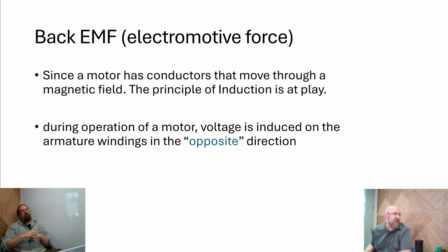This is the thing that I think a lot of people struggle to wrap their head around the first time we talk about it, because you really have to have a solid understanding of how induction works fundamentally before we can dive into the effects back EMF has on a fundamental level around why DC motors only spin so fast and how you can get only so much torque out of them. It comes back to that back EMF.